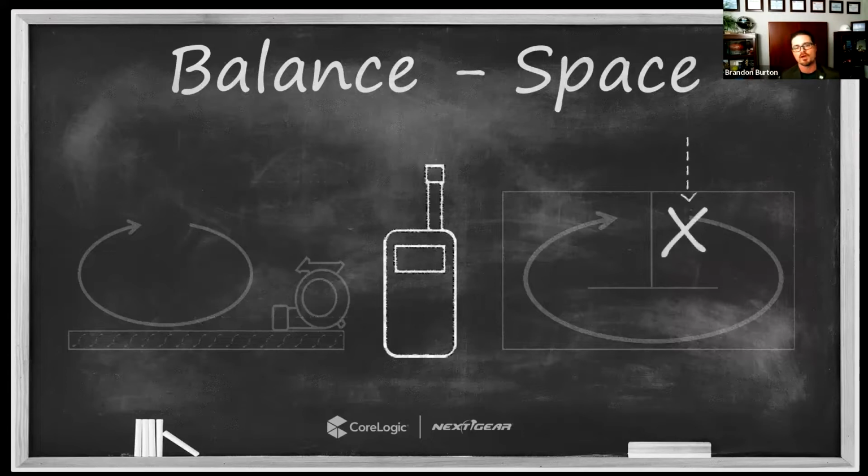The same when we're talking about the space circulation from area to area. If this drawing on the right-hand side were a drying chamber that had these 3 separate spaces, again, it's important that I measure the temperature and humidity in one end of that space and then verify at the opposite end of that space, that furthest walking distance between one area and the next, that those readings are, again, practically the same. Again, not worried about 1/10 of a degree or 1/10 of a percent, but if we're off by 10 or 20% or 5 or 6 degrees, that's significant. And it's going to have a significant impact on the rate of drying.